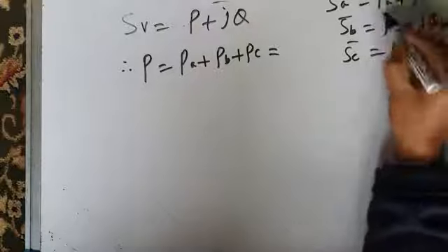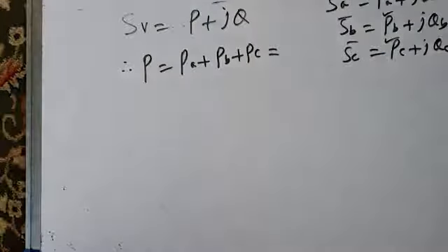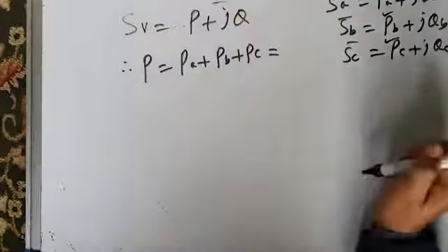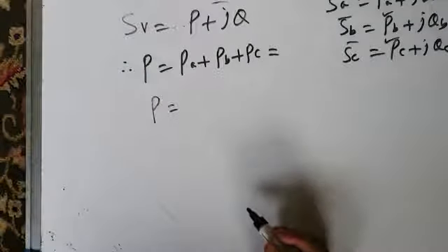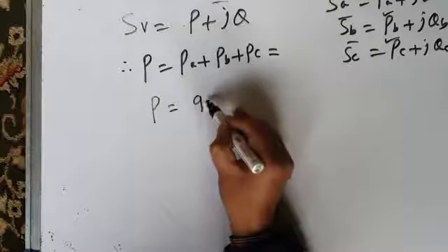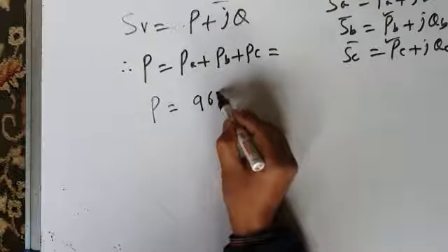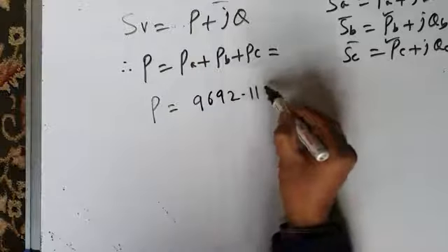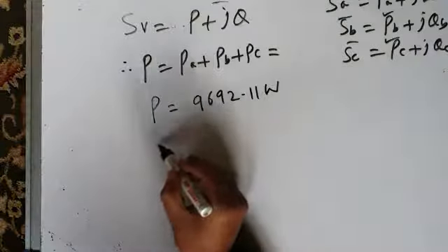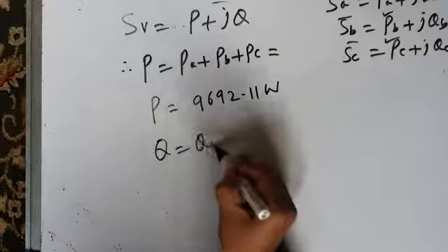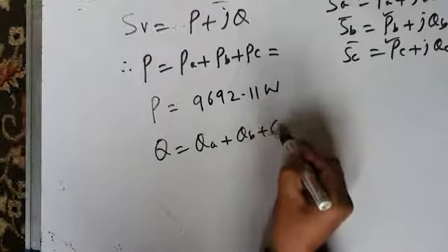If you add these three real parts, which we have just calculated, that will give you the total three-phase real power, which comes out to be 9692.11 watts.